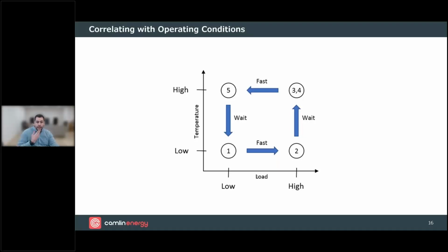Our online sensor that we've constructed for online monitoring of PD, called Intego, is focused around performing measurements in this way, collecting the online discharge data over a range of different operating conditions. This is a schematic from IEC 60034-27.